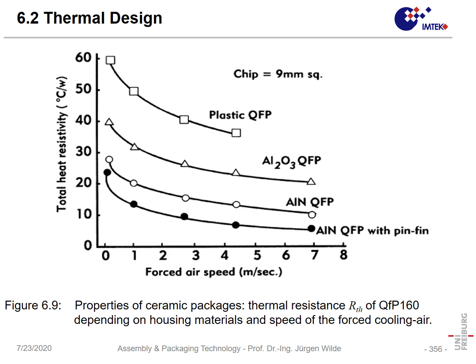Now, people have started relatively early to find out what the influence of materials is on the thermal resistance. So it's better here to write Kelvin per watt. So here we have different materials: plastic, aluminum oxide, aluminum nitride, and aluminum nitride with pin-fin.